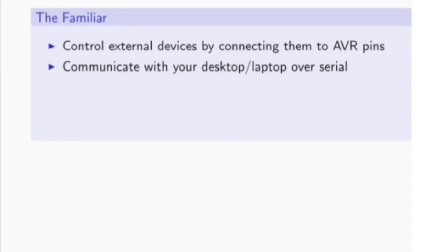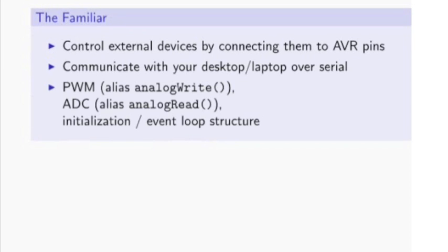And then if you need to output analog-like values, you'll use pulse width modulation, which is what the Arduino's analog write is doing in the background. And you'll be able to read in analog values using the analog to digital converter, which is what the Arduino's analog read is doing in the background.